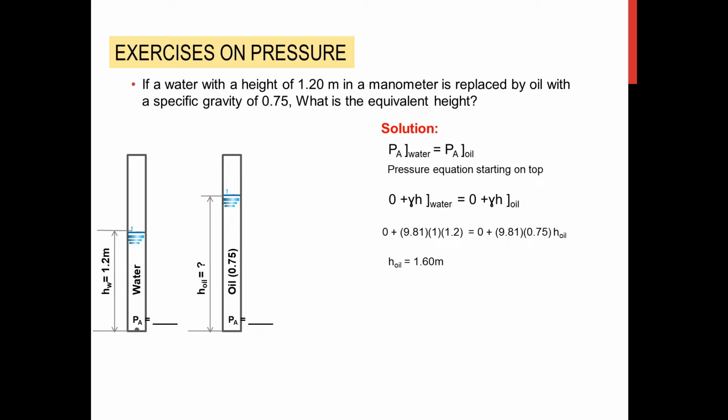Notice that the head of oil is greater than the head of water. Why? Because oil is lighter than water. Therefore, it would need to have more height compared to that of water to satisfy an equivalent pressure to that of the water.